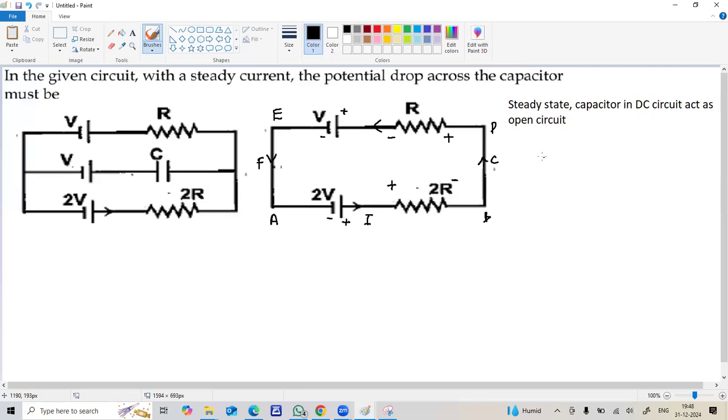So in this loop, we start from AB. The potential difference is 2 volt. You take the sign of the terminal where you exit the device. As you go from A to B, the terminal you exit from is plus. So the potential difference is plus 2V. But for the next one, when you leave the resistor, you're leaving from the negative terminal, so the potential difference is negative. This is one of the sign conventions used. There may be opposite sign conventions with different directions.